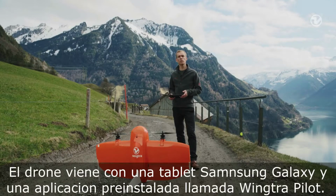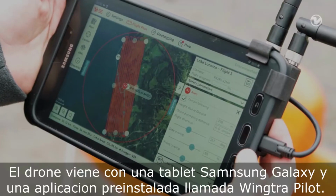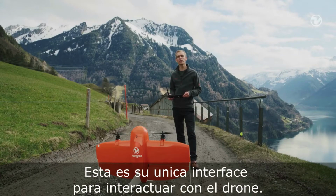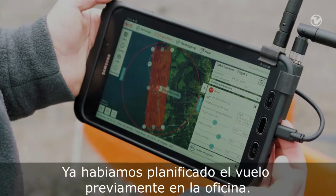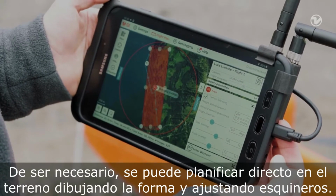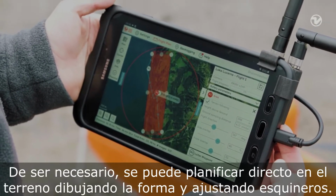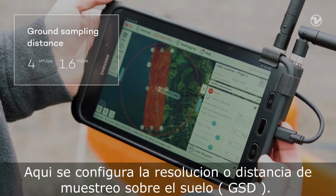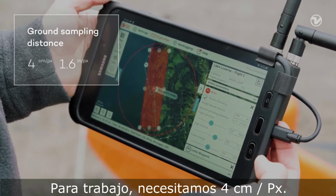The drone comes with a Samsung Galaxy tablet and the preloaded application called WingtraPilot. This is your only interface to interact with the drone. We planned the flight already in the office. If you need to, you can also plan it in the field by drawing a shape and adjusting the corners. Here you can set the ground sampling distance. For our job, we need 4 cm per pixel.